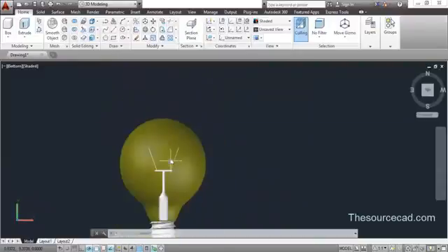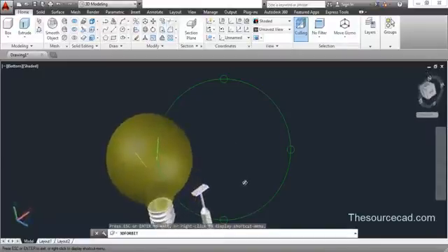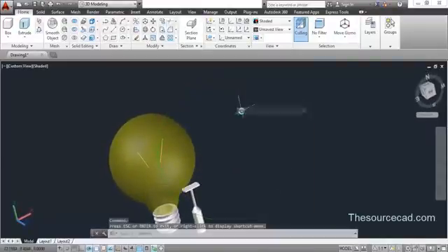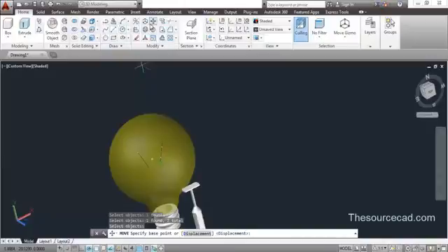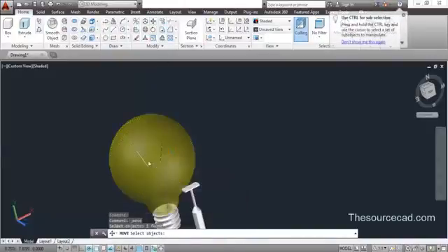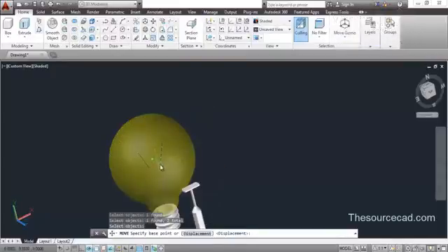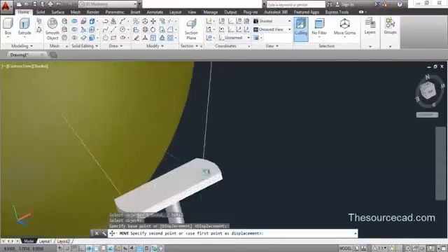Now click anywhere, upwards or downwards, and here is the mirror. I think you're aware of the mirror tool, so all you need to do is just apply a mirror to this drawing, to this particular feature. Now as you can see, it's not lying at the place where I want, so I'll select both the features. So both the lines I'll select, and I'll move it. Now go to move, and move it to a point on this.